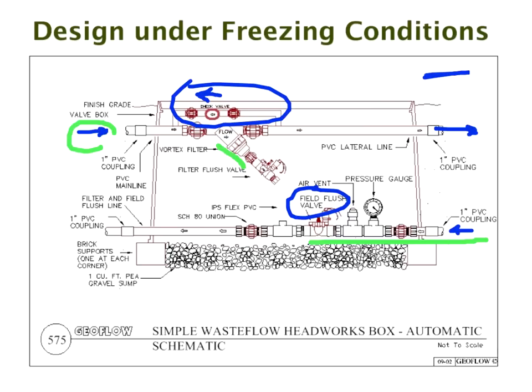So it's simple to drain this flush line. However, when you switch off, the supply line will not normally drain. It will stay full because the filter will block it from returning. You've got your pump tank and your pump, and there's no reason it's going to flow backwards through the filter and drain.